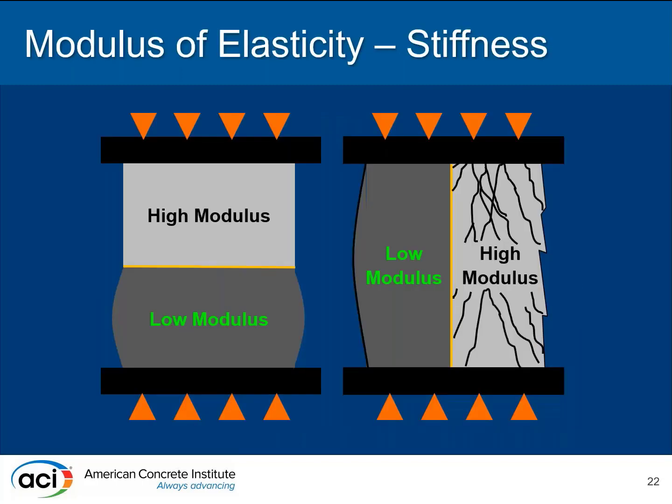Similarly, equally important from a compatibility viewpoint, and may prevent you from moving away from certain types of materials in some situations, is the stiffness of the repair material relative to the stiffness of the original concrete. Frequently the tendency is to use a really, really high strength concrete, and that can work really well, but oftentimes it doesn't. The reason is that you're not just getting the difference in strength, you're getting differences in elastic modulus.